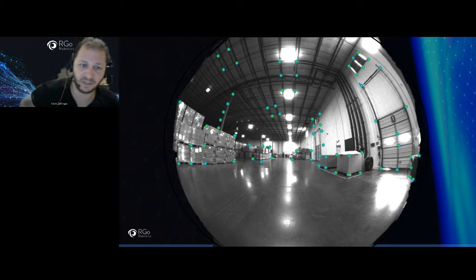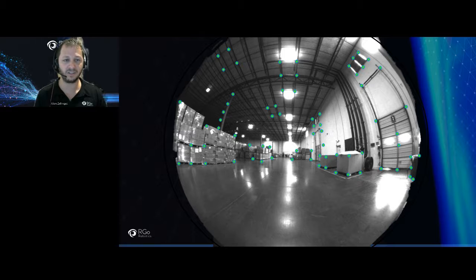What a perception engine does, and we call it a learning vision system, it will keep learning the environment, looking for unique descriptors and structures in the environment. So in this example, you can see the door and the ceiling, and it will continuously look for hard structure you can rely on. And that's okay, because even if the next round they will move, it will know, okay, this is less strong, I can still relocalize myself on these ones and maintain a strong database of how the map looks.